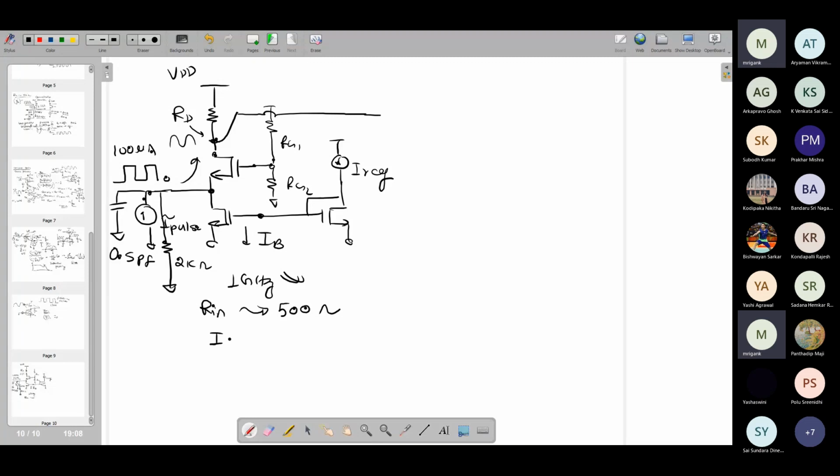So here, depending upon the bias condition, if the DC point itself is relatively lower, then you can use basically an NMOS stage. If the DC bias point that you are keeping over here is relatively higher, you can use a PMOS stage. You can also use the circuit that we had discussed the other day, right? Yesterday we discussed this particular circuit, which can also achieve a good gain. Basically, it can give you almost full swing output.